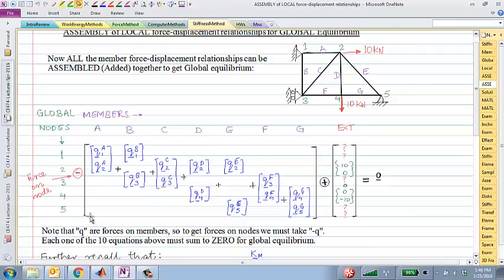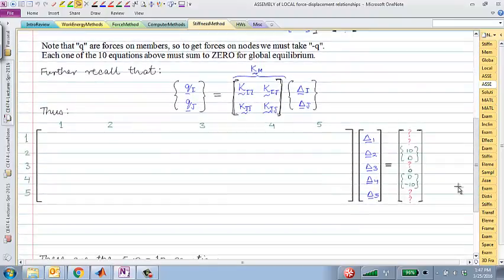What we're going to do now is to convert each one of those element force vectors to something that looks like a big matrix, which we'll fill in, and actually that I'll ask you to do as an in-class exercise after I show you a couple of examples, and then multiplied with the unknown displacements. So displacements at 1, 2, 3, all the 5 nodes, both in the x and the y direction at each one of those nodes, those are the unknowns that we are trying to solve for.